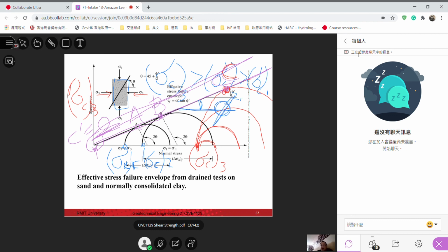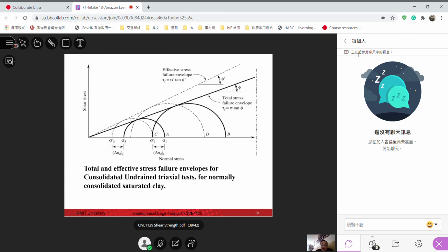Okay, so angle of friction here, cohesion intercept here. So those are the 2 parameters that we need to determine. Of course, here we just talk about the theory, maybe a little bit for you to understand. But when you actually do the test, it will be much easier. But the concept of the triaxial test is like that. The concept of the direct shear test is similar.